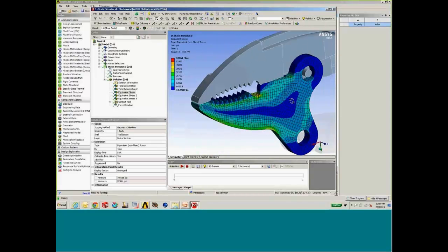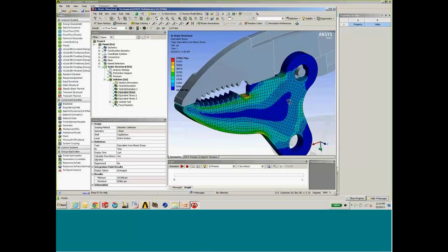So my options for evaluating this type of situation are two, basically. I can refine the geometry in the global model and regenerate the entire global solution. Not really a big deal with this model because it's not terribly large. But if I had a very big, complex assembly, I may not want to do that. I may want to run that global analysis one time and then utilize those cut boundaries to evaluate the stress and maybe even do a mesh refinement study on a local level using the submodel. So that's what we're going to do today.